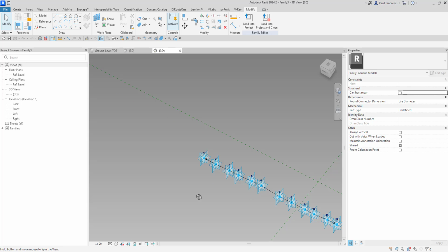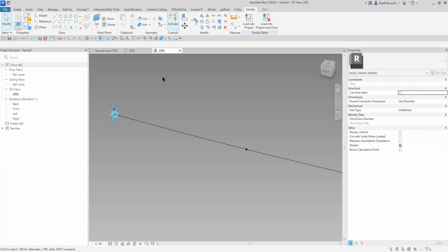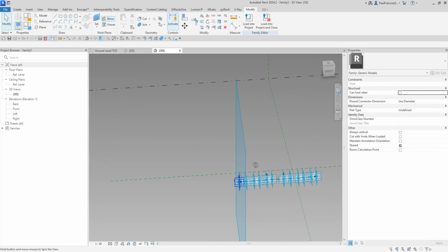Right, and then we need to generate some geometry. To generate the geometry, we're going to use that point over there. You can see it exposes a reference plane, so we can actually say set the reference plane. We can pick onto that point. That now sets the reference plane. If we show, you can see how that reference plane is showing around that point.